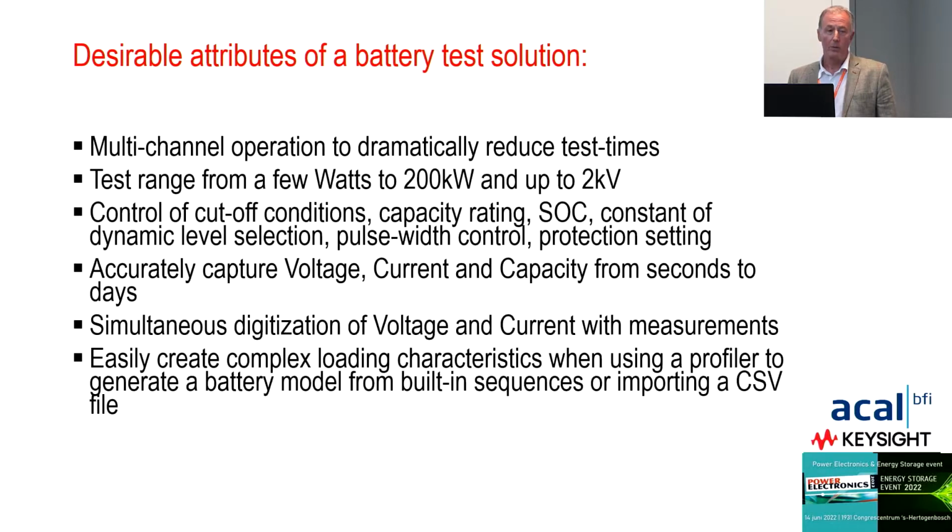It may well be that you want to run your test maybe for a few minutes, maybe for some hours, maybe days or even weeks, just to see how the device performs. So you need to be able to capture that, and you want voltage and current and capacity in order to be able to accurately model what's going on with your device. So we can simultaneously digitize voltage and current, so you're then able to measure energy and power from the cell.